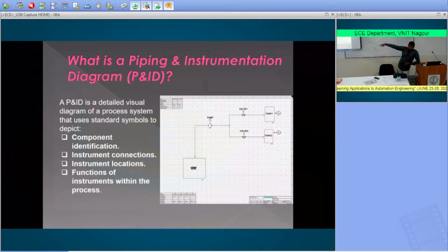So one sump is there. From that, the water management will happen in that one area. In that area there will be 2 tanks. From that sump, the pump will pump the water to one tank, and there will be 2 level sensors also. And each valve will be an electrically operated valve. So once it reaches 70%, 80%, the valve will be closing, and another valve will be opening, like that. Different scenarios we can create, and that is also possible in this.